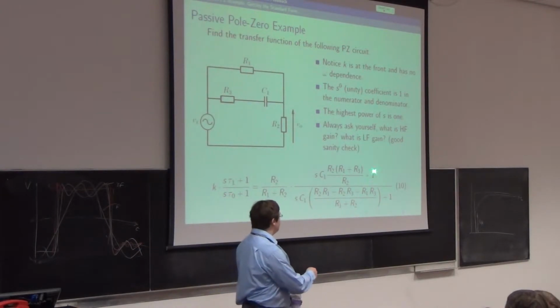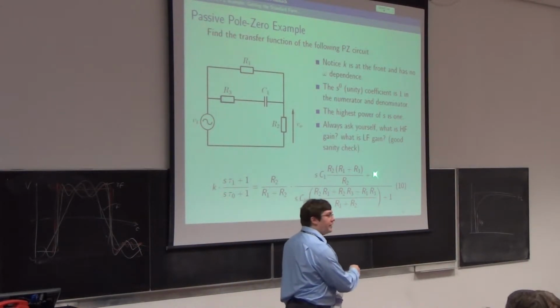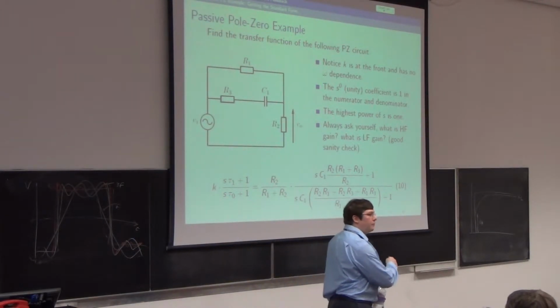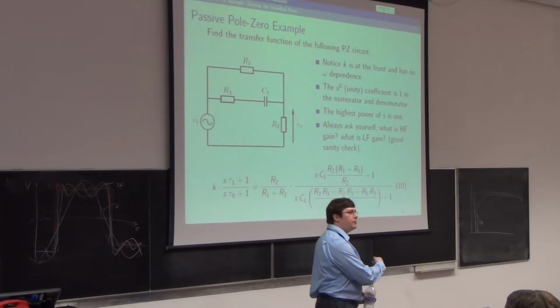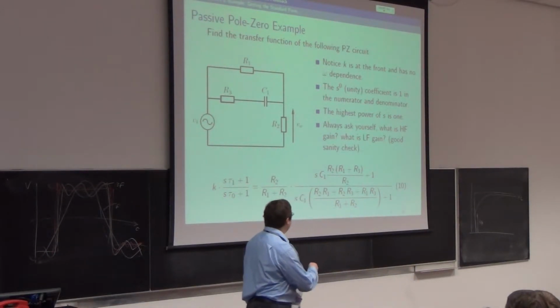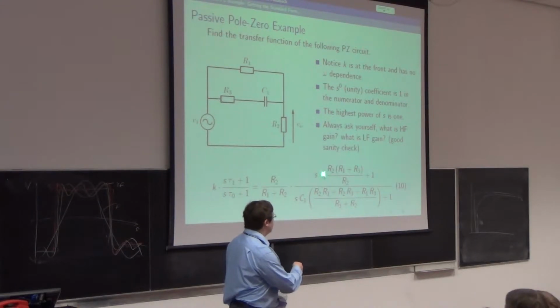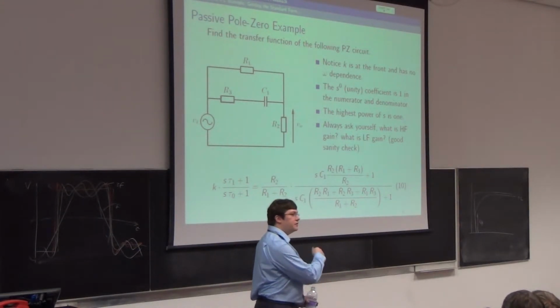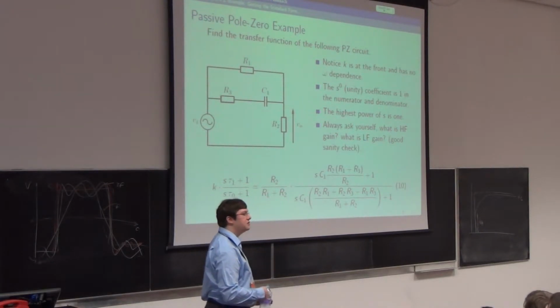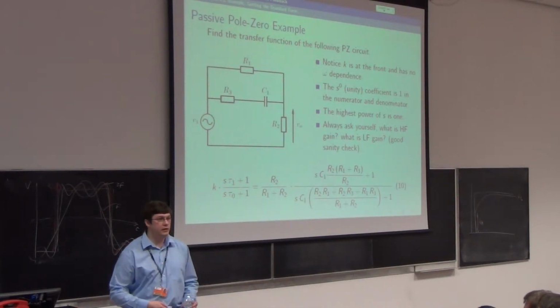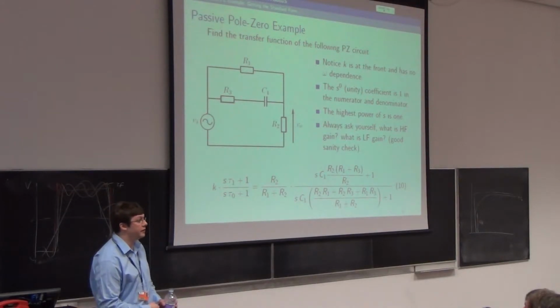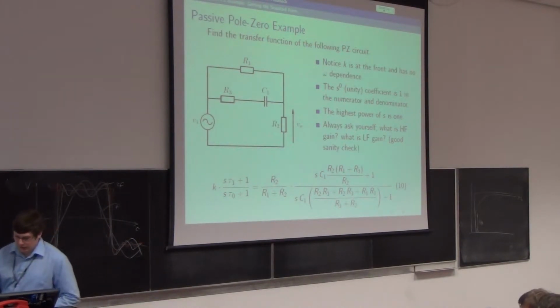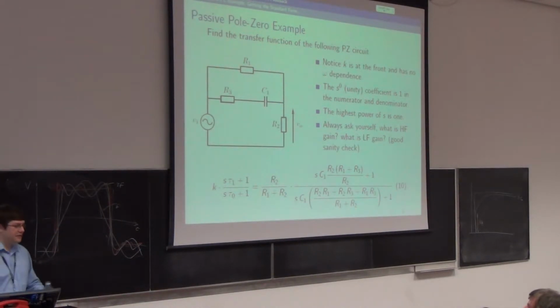And we must make sure we get 1 here. We can't have a multiplying factor through our polynomial. If you want to get the tau, the right value, this has to be 1 and this has to be 1, and you have to order your mathematics to make it so. If you don't, you will get the wrong time constant, and I will laugh at you. Not publicly, obviously, just when I sit there looking at the scripts, I'll giggle.